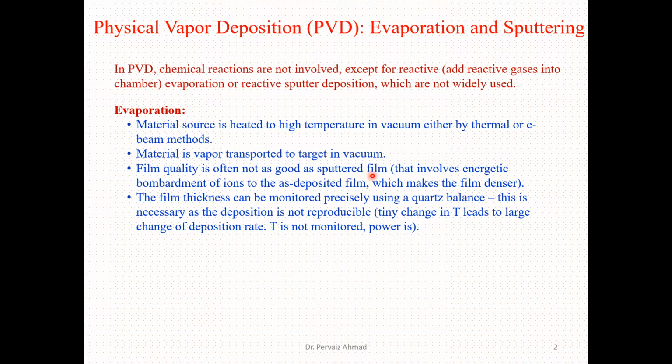Remember, sputtering techniques normally involve energetic bombardment of ions onto the deposited film, which makes the film denser. And the evaporation technique can be monitored precisely by using a quartz balance. This is a good characteristic of the evaporation technique, with which we can monitor the film thickness.